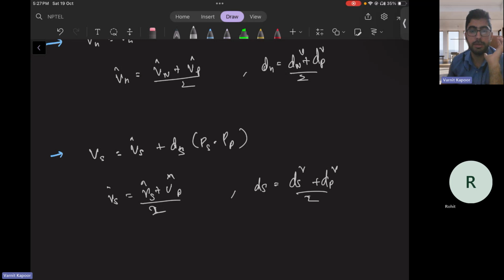So the idea is similar to SIMPLE. You would wish to have these flow rates or velocities corrected such that they satisfy the continuity equation. We want to address the corrections, that is U star for east, west, north, south, and V stars for all the phases.